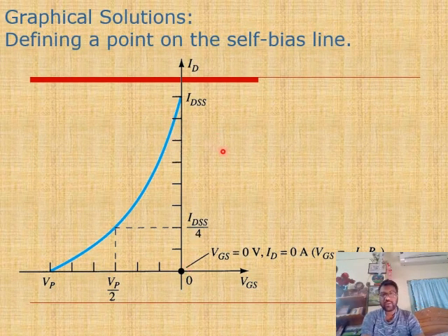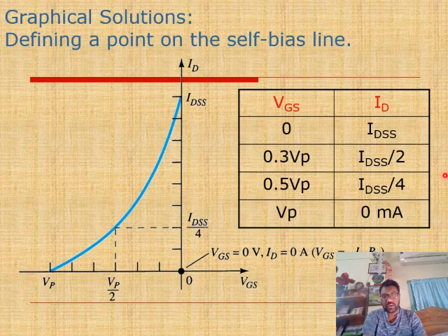And this graphical representation denotes the previous self bias circuit with a single source, where we can see this is the pinch off and this is the IDSS. Now VGS is 0 at ID equal to 0, VGS is minus ID RS at this point. So Vp by 2. As per the value of IDSS, Vp or VGS, this graph can be drawn.